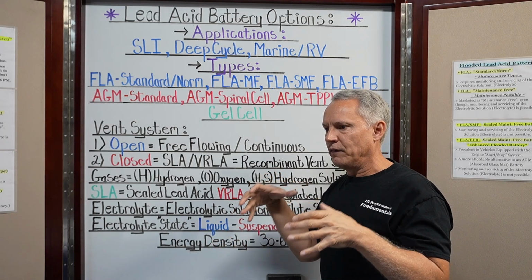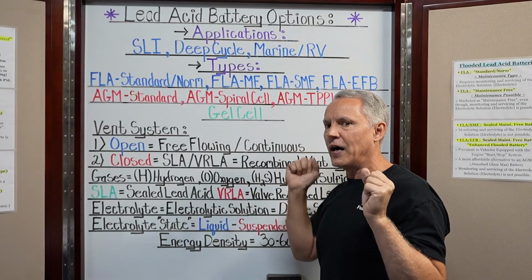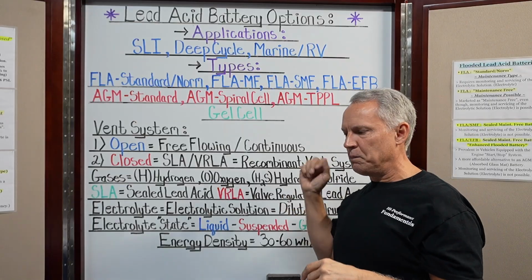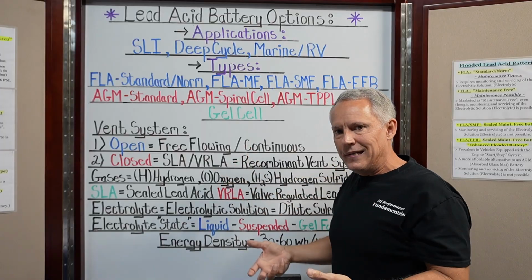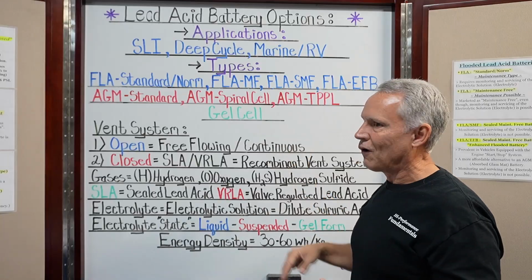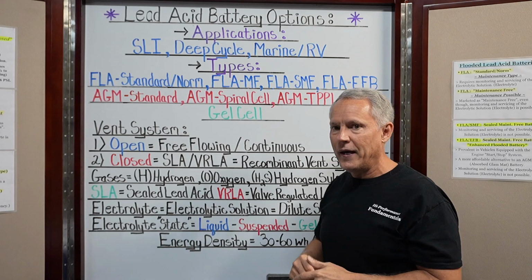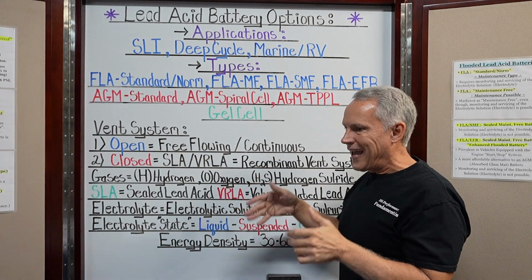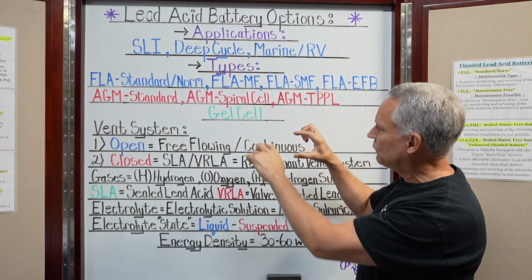Yes, it does store a certain amount of electrical energy, but as you deplete it, the chemical reaction process continuously takes place and provides more and more electrical energy. So it's not just stored. It's stored and it's actively providing electrical energy. Both. Now, depending on how much the battery physically weighs, and not so much the case, the casing is pretty much the same on almost all batteries. Your external terminals are not really the weight either. What we're talking about is the actual plates inside the battery, the cathodes and the anodes, what they're made out of, how much they weigh, and how much energy they have for any given surface area.